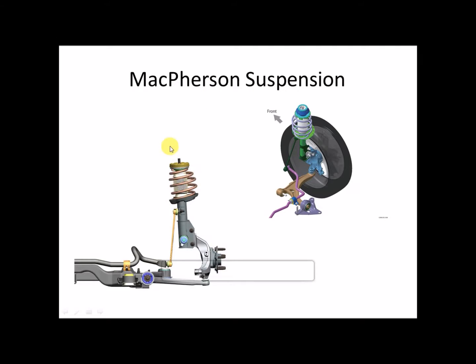This is a strut. That is the pre-compressing of the spring. The advantages of that are more space and the loads are better distributed, but we have other disadvantages. That is small values of anti-dive and lift and little design flexibility.